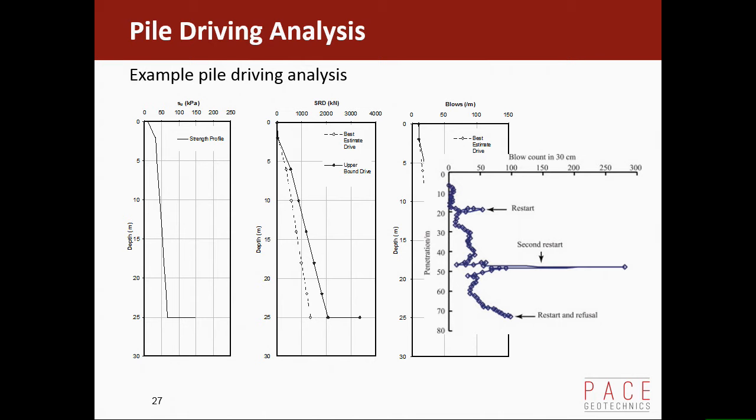You get an excess pore pressure generated, it dissipates, and the clay particularly recovers its strength. So you've got to hit it harder to get it started, and that is quite an important one, particularly as you see here. It's taken really quite a lot of blows to get it started, and that can impact on your fatigue life as well if you're not careful. But once it's started going, look how far it's come down, 1/6 of the blow count. So it's that sort of thing you need to be aware of.